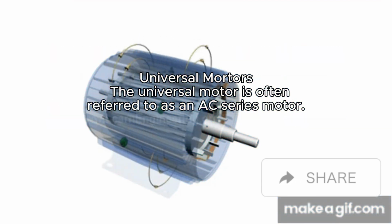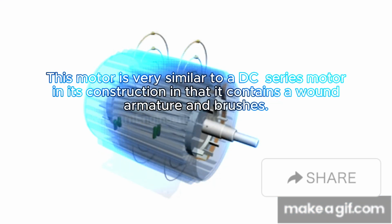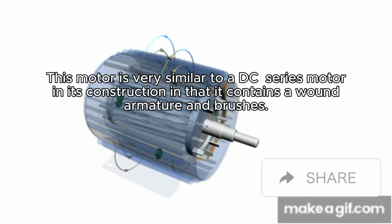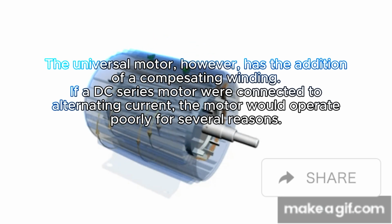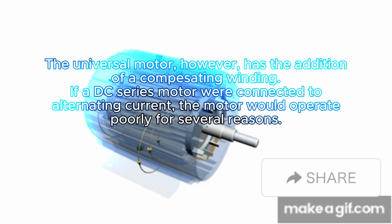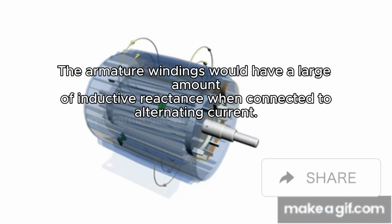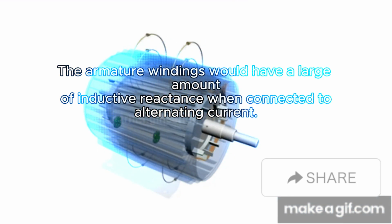The universal motor is often referred to as an AC series motor. This motor is very similar to a DC series motor in its construction in that it contains a wound armature and brushes. The universal motor, however, has the addition of a compensating winding. If a DC series motor were connected to alternating current, the motor would operate poorly for several reasons. The armature windings would have a large amount of inductive reactance when connected to alternating current.